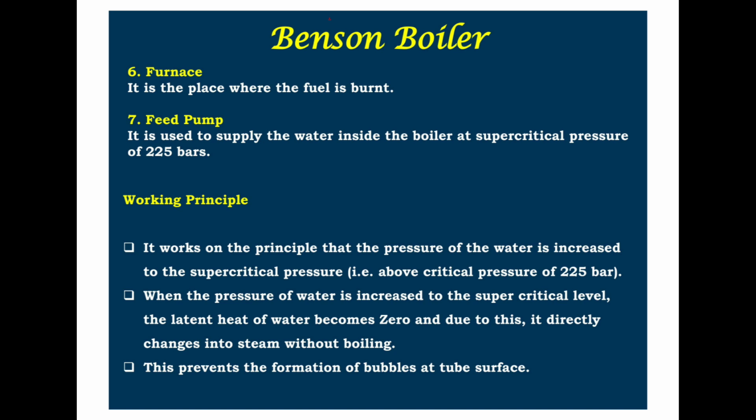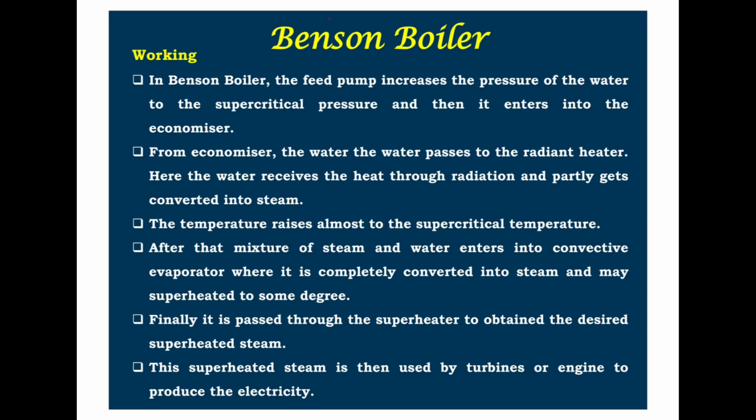Now the working principle. It works on the principle that the pressure of the water is increased to the supercritical pressure, above the critical pressure of 225 bar. When the pressure of water is increased to the supercritical level, the latent heat of water becomes zero, and due to this it directly changes into steam without boiling. This prevents the formation of bubbles at the tube surface.